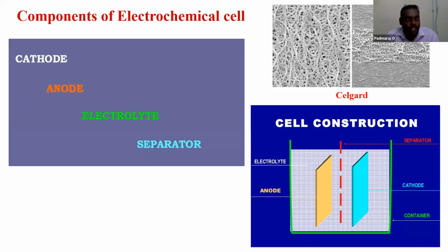That is due to the electrolyte evaporation during the operation, charging and discharging. Suppose you do many cycles of charging and discharging. What will happen? The internal temperature will rise, so the electrolyte gets vaporized. That bulge is nothing but the vaporization of the electrolyte. Also, due to the internal temperature, the separator may shrink. If the separator shrinks, what will happen? The anode and cathode get short circuited, and then the battery explodes.